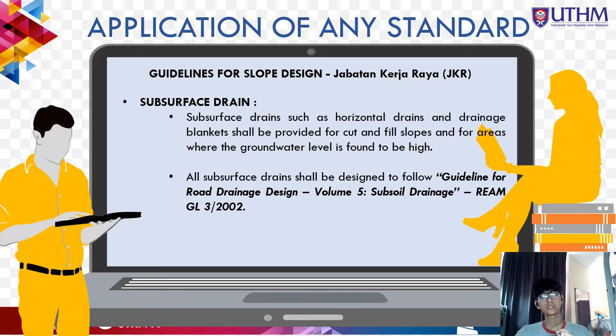For subsurface drainage, such as horizontal drains and drainage blankets, they should be provided for cut and fill slopes and for areas where groundwater level is high. Lastly, all subsurface drains should be designed following the Guideline for Road Drainage Design, Volume 5 Subsoil Drainage, REAM GL 3/2002.